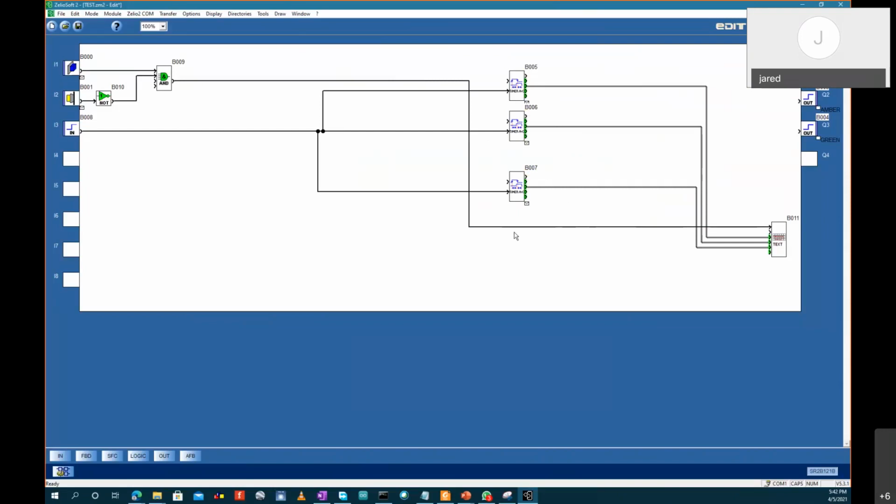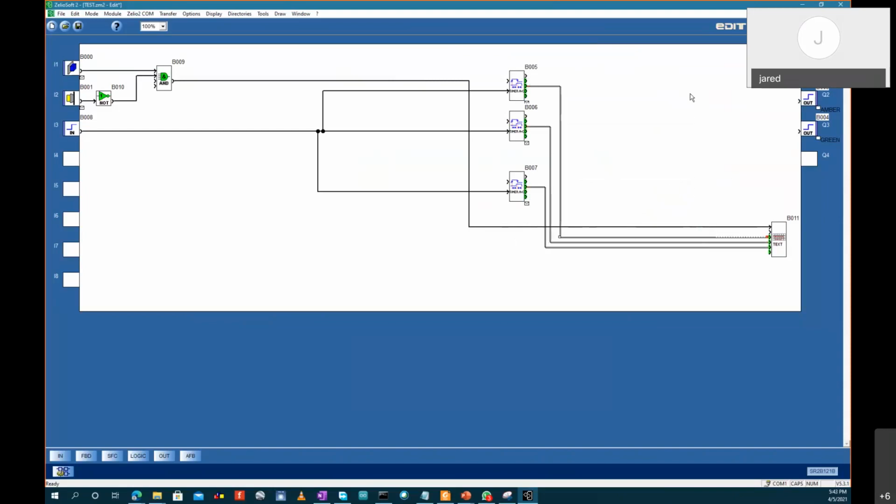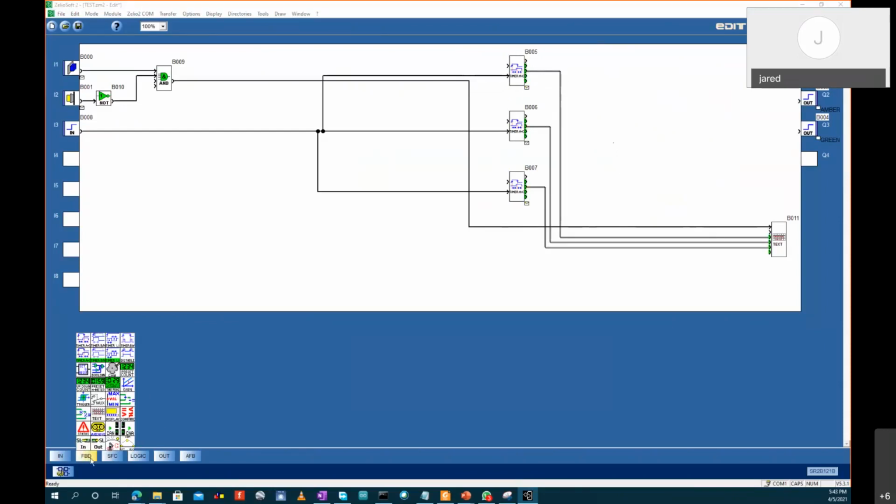So you need an AND gate to perform that operation. And how is the AND gate going to be incorporated in the circuit? You're now going to call an AND gate and program it, so that before the timer is done, I should not go to the next step. So this guy can go up, up, up. This guy can just remain there. And now you need to call an AND gate. So you go to the logics, call an AND gate.